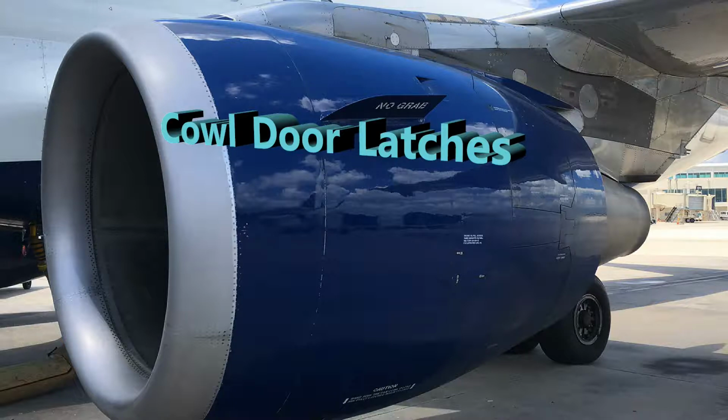And then you're going to press the down button so that those fan cowls start to go down. Then when both of the cowls are lowered, you're going to close the latches, and then you're going to close the access panel by securing those 5 catches on the panel.